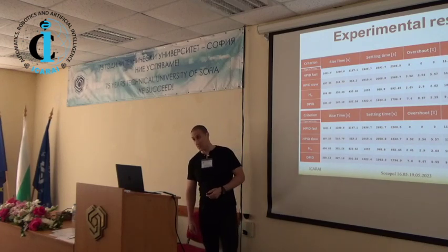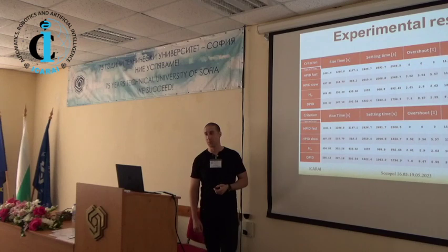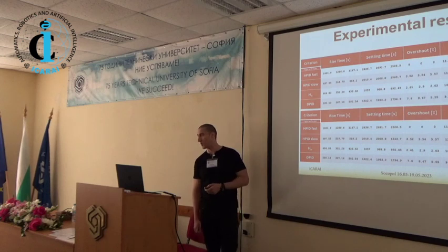The graphical results and the numerical ones show us that for this particular case, the use of this hinfstruct function, which I forgot to mention, solves the problem of H-infinity design of the control for fixed order, fixed structure. It shows comparable performance with the full-order H-infinity controller, as with the, at least interesting to me, simple decentralized PID with only a static decoupling matrix.